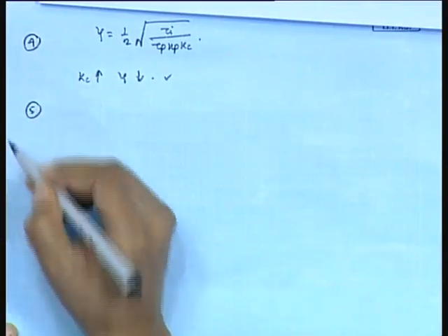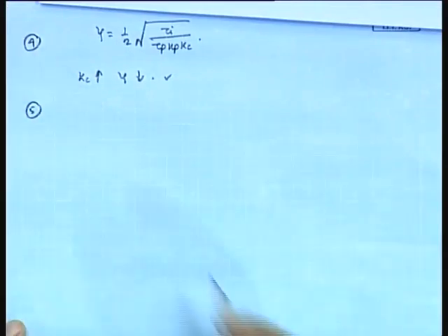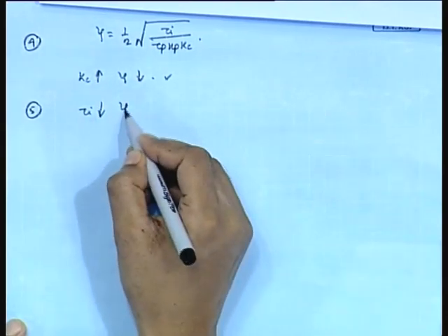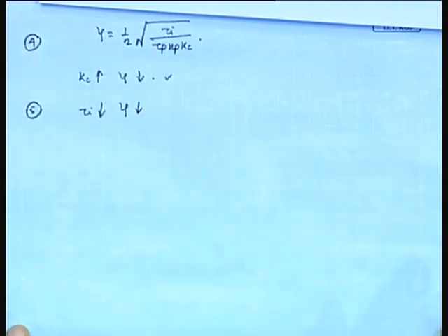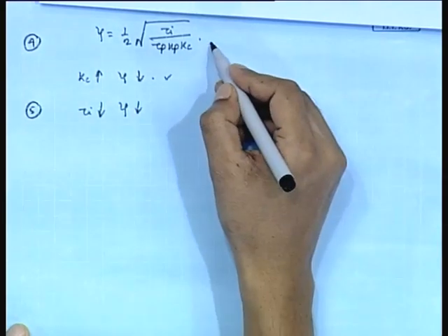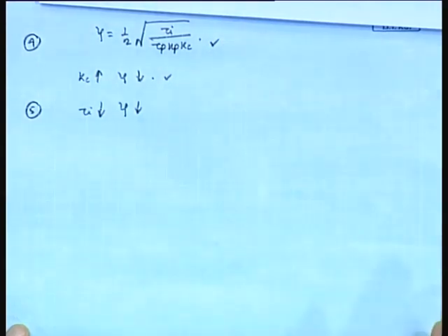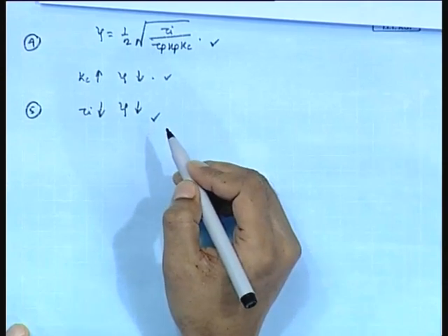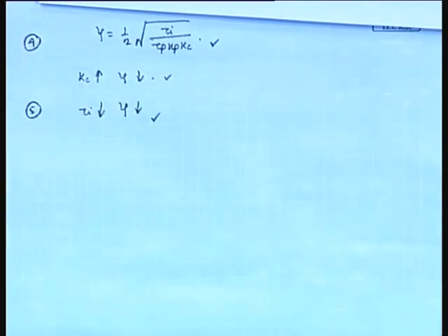In the same line, we can conclude again that with the decrease of tau I, zeta decreases. You see the expression of zeta, it is clear. So, if tau I is sufficiently small, the overdamped response may move to underdamped response with large overshoot and decay ratio. Fine.